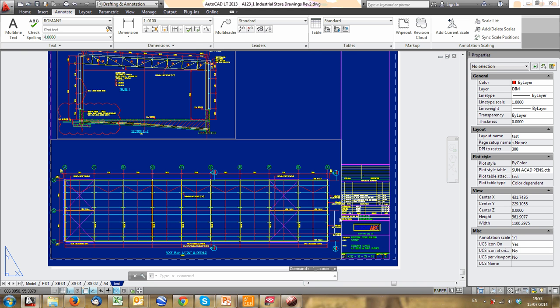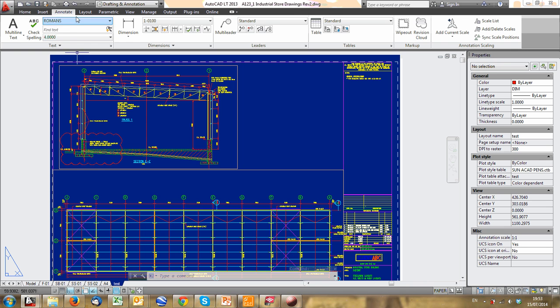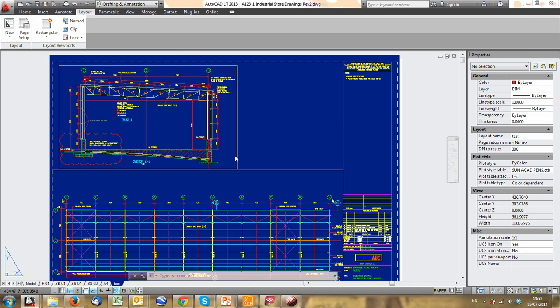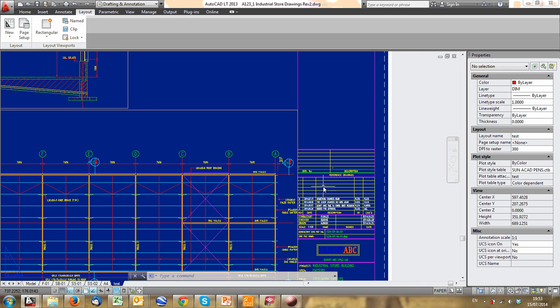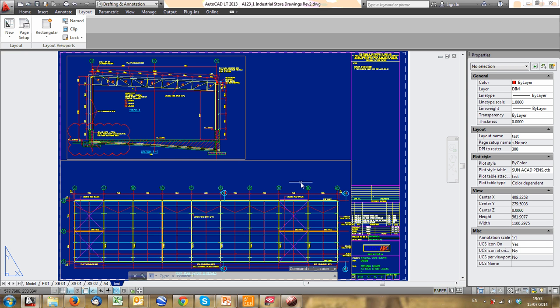And that more or less covers title blocks. So you can at least now set up a title block, create viewports, edit your title blocks, and generally produce a drawing. You add your standard notes to the side, put all your information, your concrete strengths, your steel specifications, your earthworks details, your standard SANS 10400 or whatever it is you're using, and you can go through and give all the details required and all references that the contractor, client, whoever might need to refer to find that information.